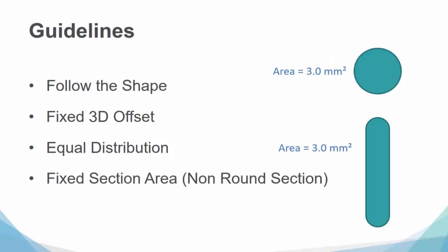Now, looking at the water line itself, one of the key ingredients is to keep the cross-section of that water line uniform. So maybe I'll change the shape of it as I direct it around certain mold details. Like in this example, maybe I would go from a round diameter and need to squish it sideways to get between a couple of ejector pins. If I do that, I also need to elongate it so that I maintain that constant 2D area of the cross-section. That becomes important so that the same volume of water is going through that water line. And that's true no matter what shape I use when it comes to that section. We'll illustrate that further with another example.